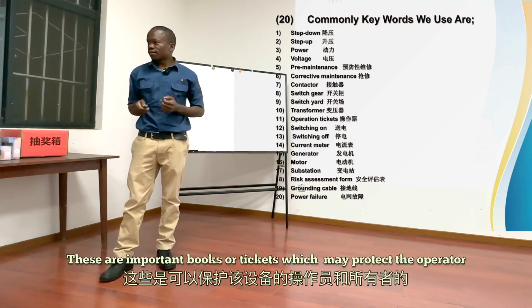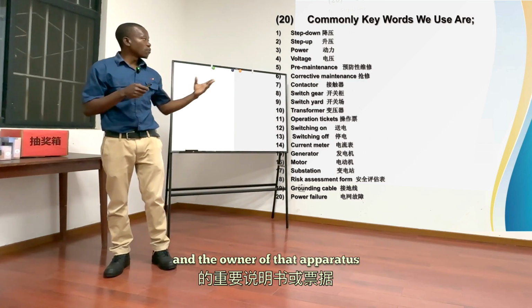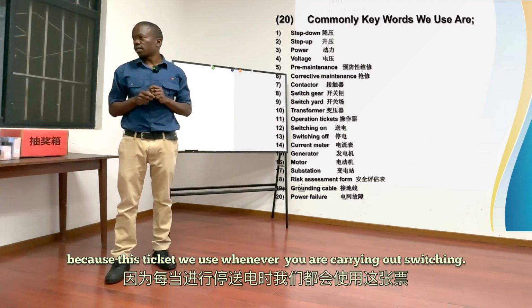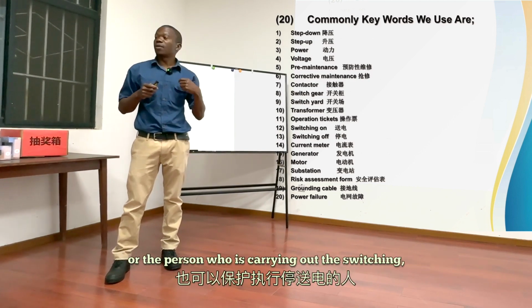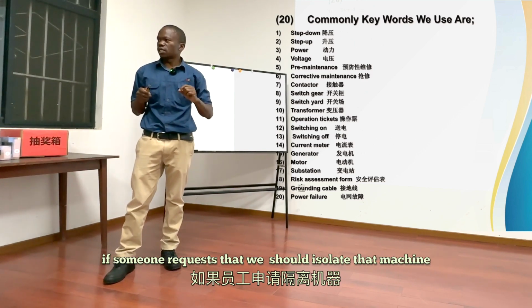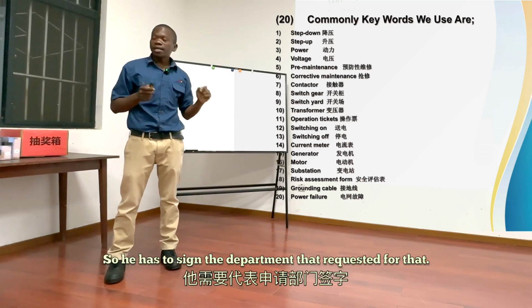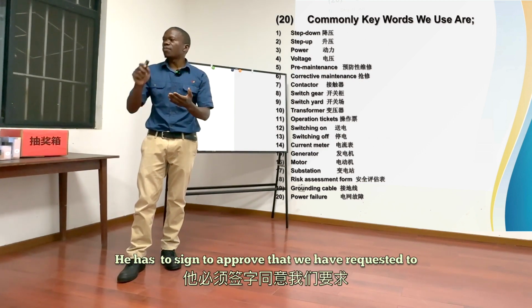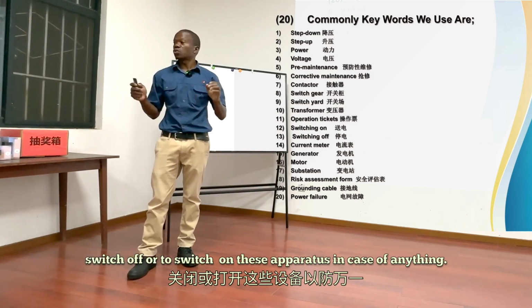Number 11, operation tickets. These are important books or tickets which protect the operator and the owner of that apparatus, because we use this ticket whenever we are carrying out switching. It protects the person who has requested and the person who is carrying out the switching. If someone requests that we isolate a machine, then he has to sign. There are two types: switching on and switching off. The department that requested it has to sign to approve that we switch off or switch on this apparatus.